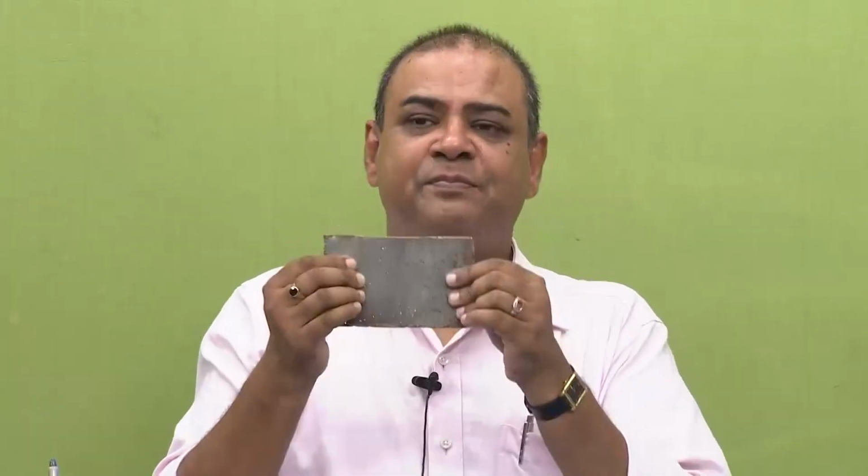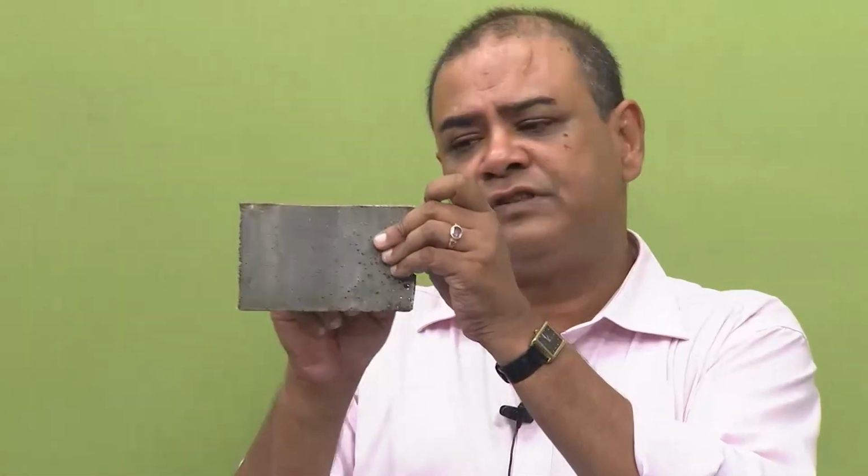That is why pitting corrosion is so dangerous: it will not give you any signal before a fracture happens. Though we are able to see these big holes, sometimes these holes are so microscopic that unless you go under the microscope you will not be able to see them, but actually the plate has been punctured and the cross section thickness reduced. So, this is a severe mode of corrosion when we talk about the 8 forms of corrosion.